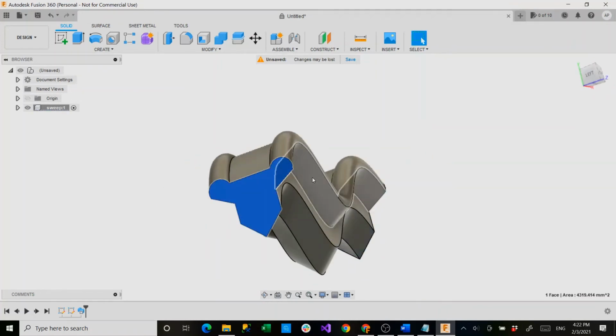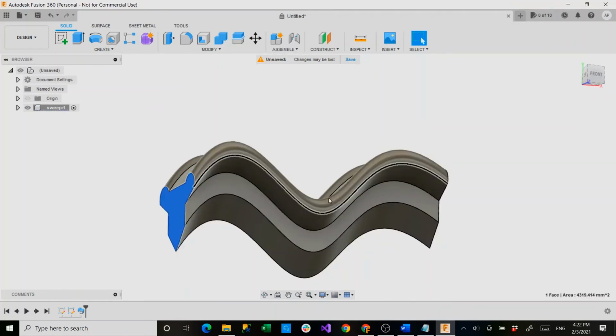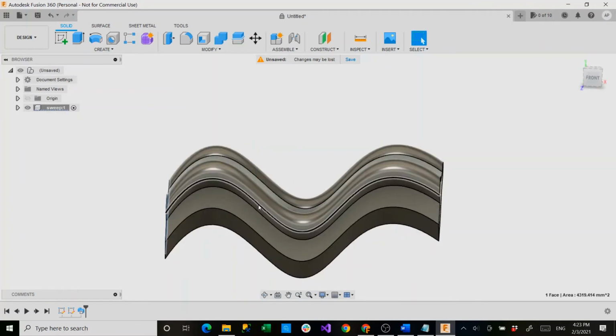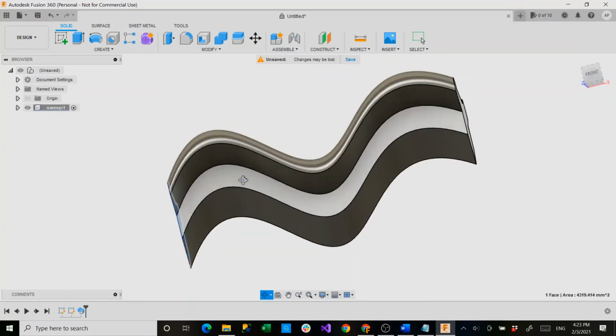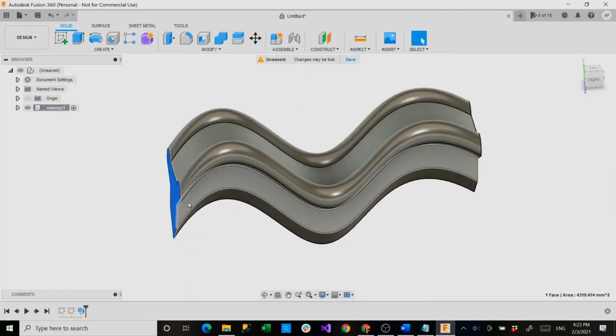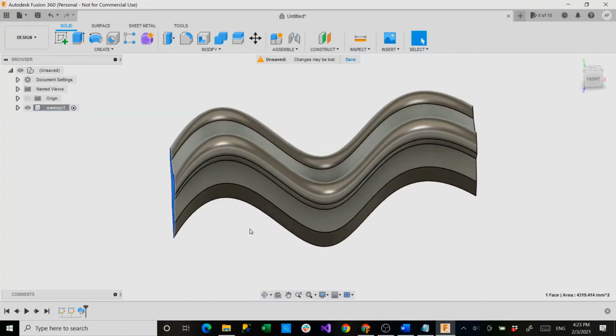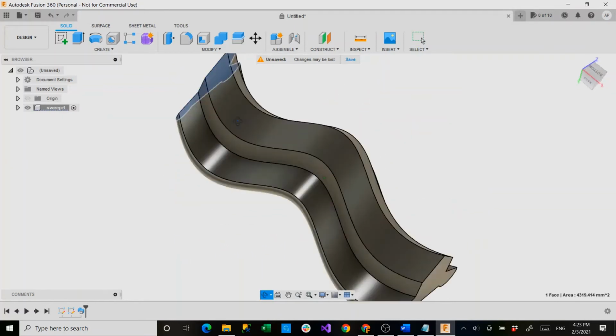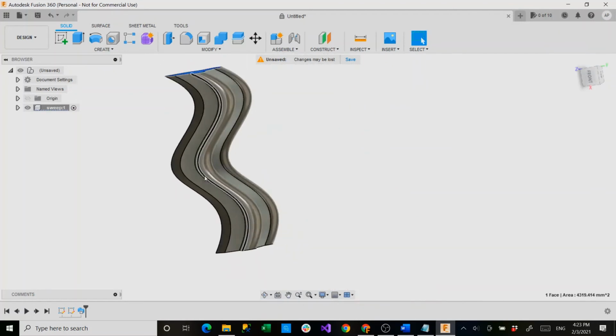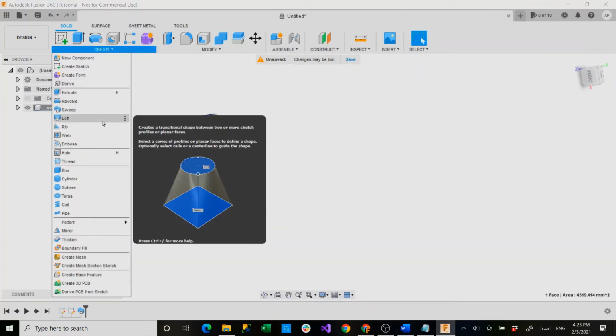We have two faces and a body that connects them, fitting a fit point spline. This is good if you're making tubing, piping, or connecting two objects that have the same endpoints and you need it to connect around an object. You can use this sweep profile to connect those. In future tutorials, I'll give specific examples of why you would use these profiles, but for now, just go by my explanations. Now with that set up, I'll show you how to use the loft profile.